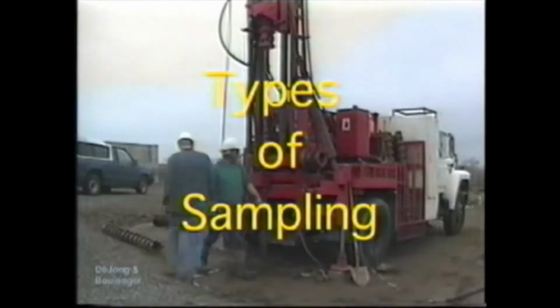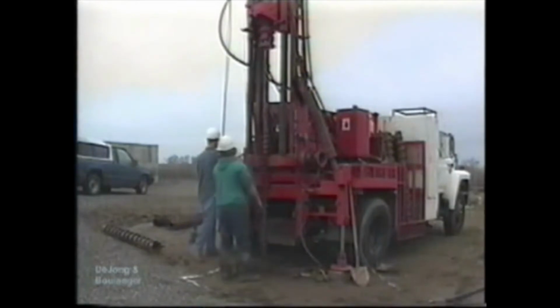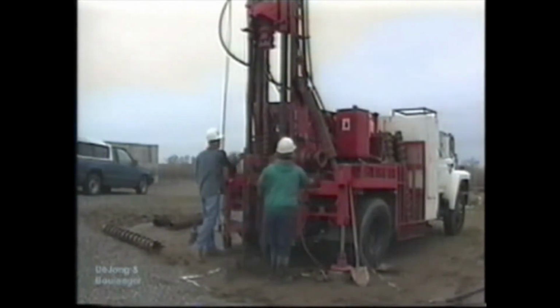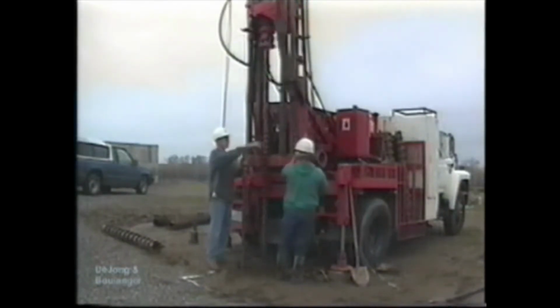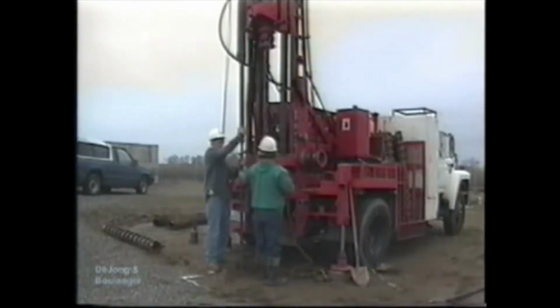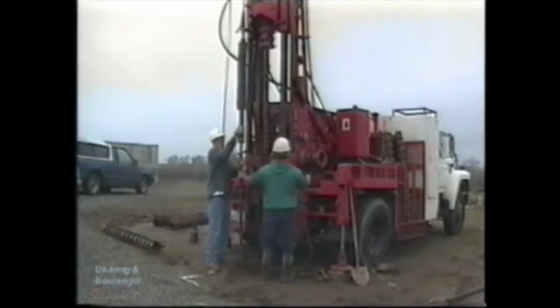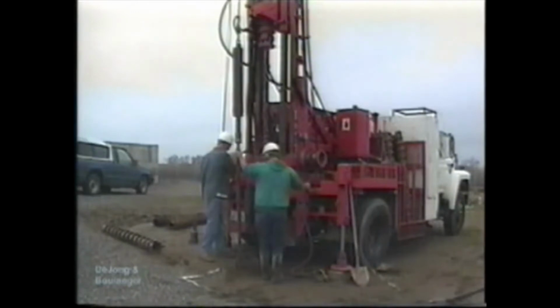We will now discuss methods used to sample soils, thereby allowing the characteristics of soil at discrete points to be evaluated. The choice of sampling method depends on the intended use of the soil samples. Lab measurements of engineering properties, such as strength, stiffness, compressibility, or permeability, can be strongly affected by sample disturbance. However, time and costs increase rapidly as the degree of sample disturbance is decreased.